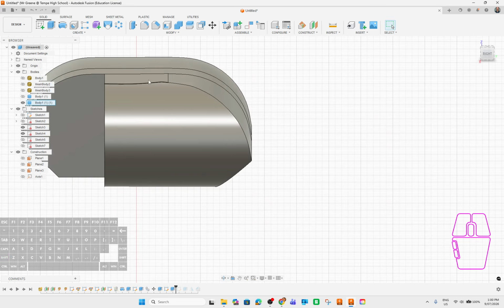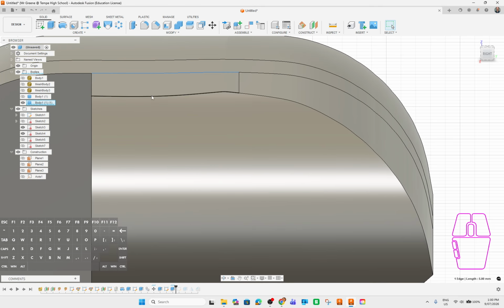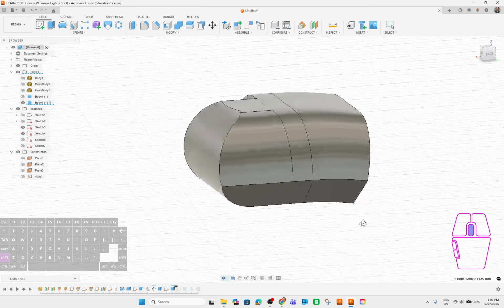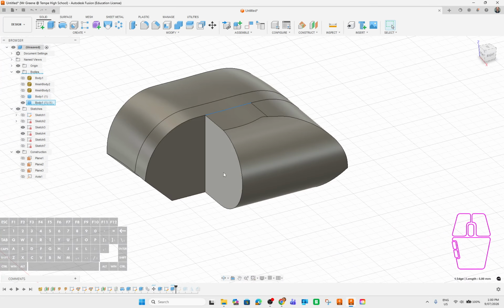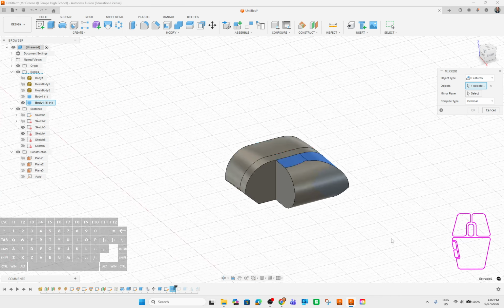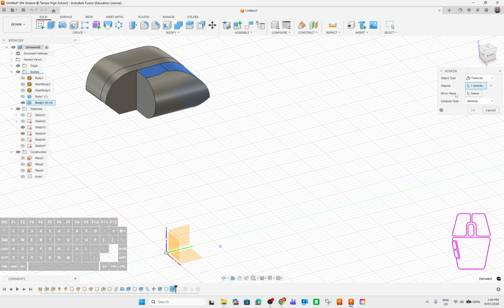Okay, so this may be a little bit of a curved sketch, probably a product of that spline tool, so that should be a flat section. No big deal. Okay, so now I want to do what I just did and mirror that. Go grab this one.